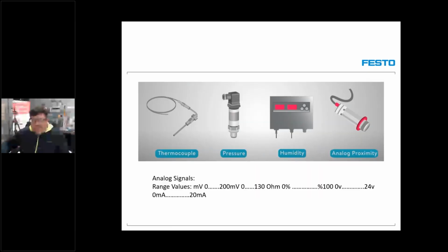All right, now here I've got a summary of sensing devices, but this time for what we refer to as analog signals. A PLC can take what we refer to as binary signals, that is discrete inputs, that are on or off, but we can also have input signals called analog signals. Now, analog signals have a range. For example, I normally compare it to 0 to 100. That means you can measure anything from the point you start to the end, from 0 to the end.